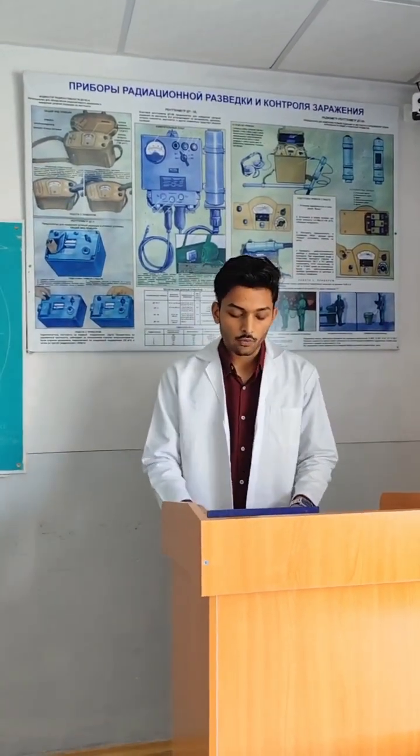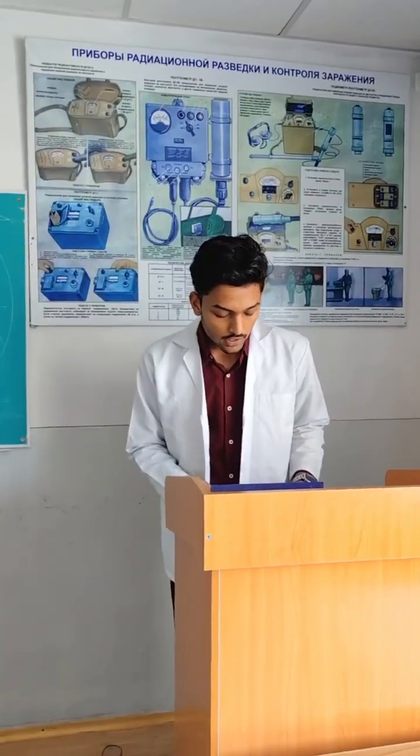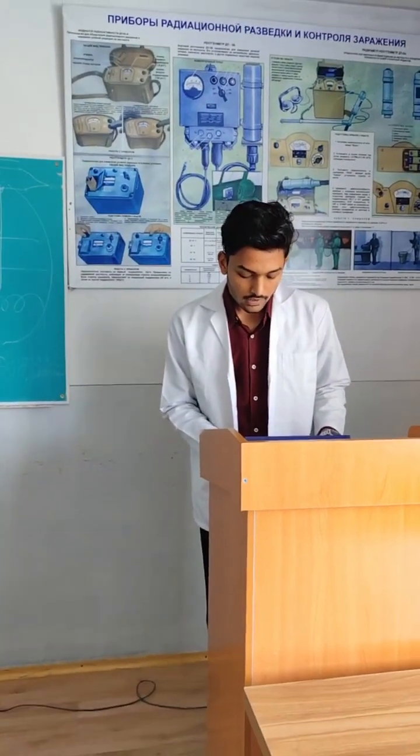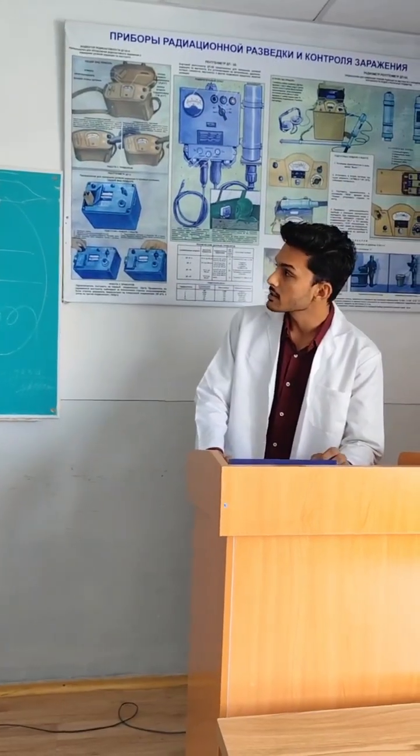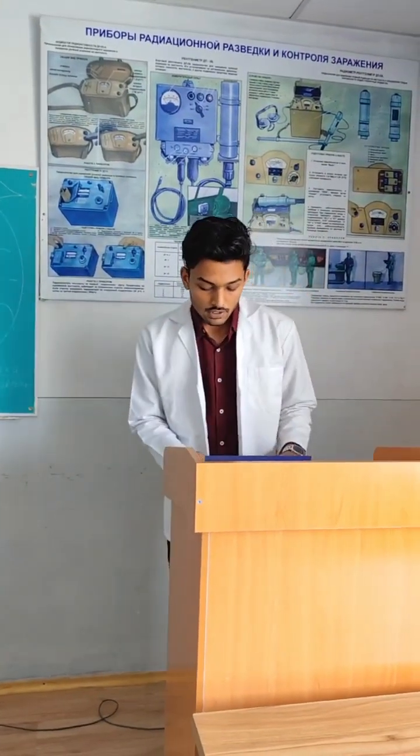Uniform and shadow-free illumination, 200 to 300 lux in wards, 500 lux in operating areas, use of UV lamps for disinfection and emergency backup system required.